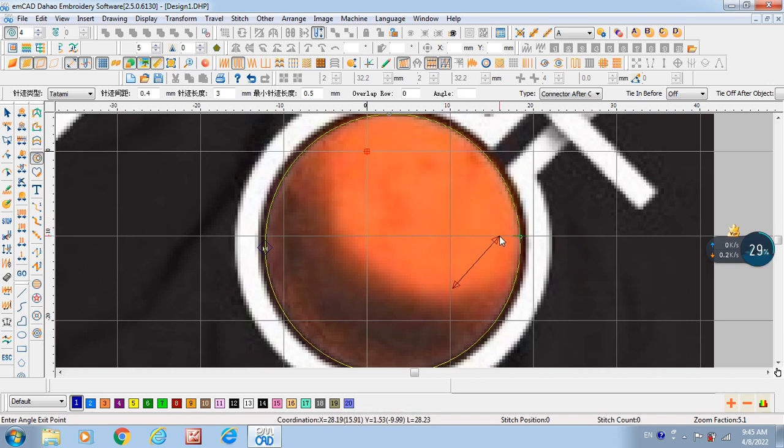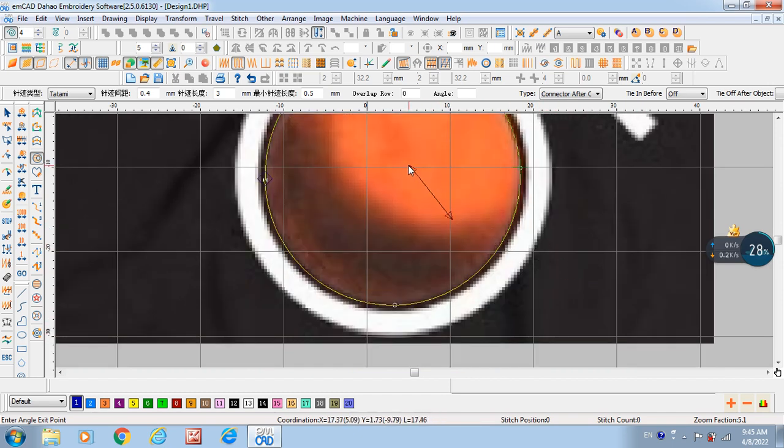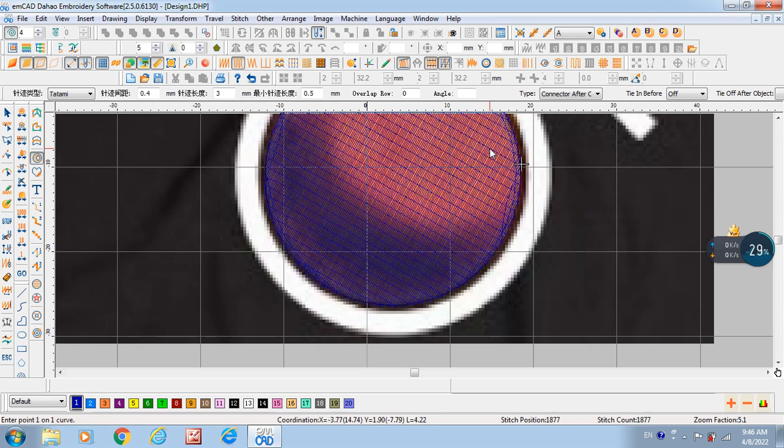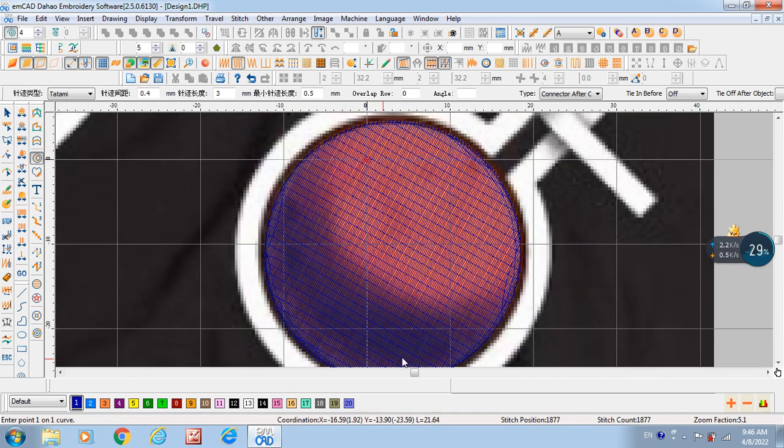I make it maybe like 30, 40, 45. Normally for field like this, I make it 45. It give me good effect. So 45 here. I choose 45. You can just okay, click, then leave. Left click again, it will fill the area here. Now I have a tatami.